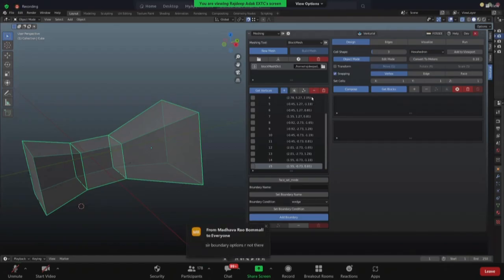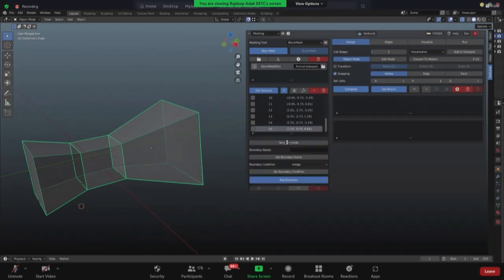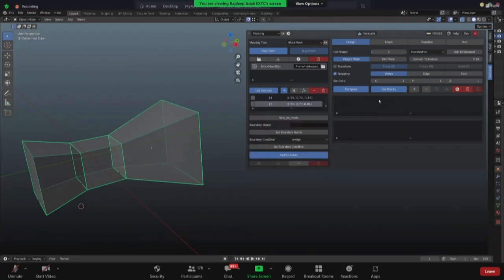And be sure that if you're deleting a vertex, you are very sure that you don't need it, okay? So this is how you get your vertices. In the same way, when you need an ordered pair of vertices to be mentioned for your blocks, that is how you define your blocks. I think the way you do that is by the right-hand thumb rule around the base of the block, and then go towards the X direction, then towards the Y direction, and then towards the Z direction, right?